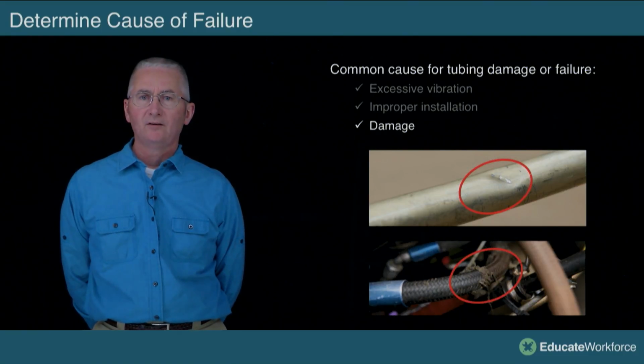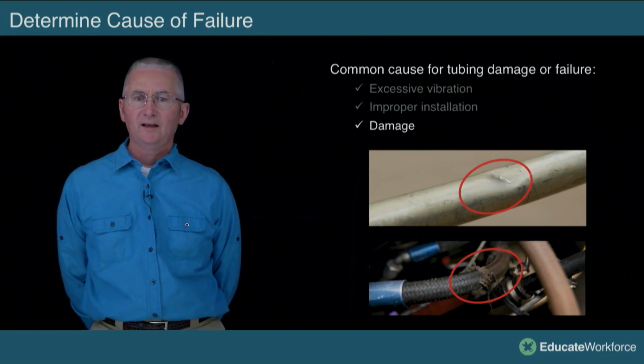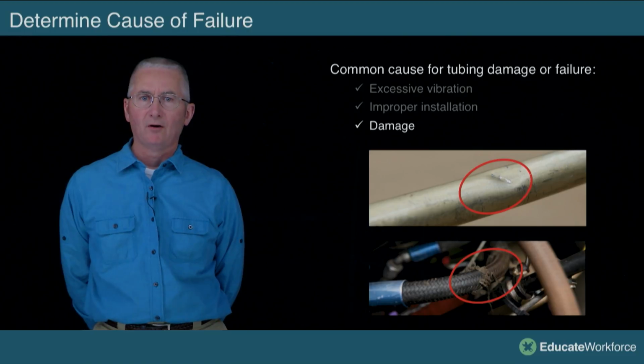And here's another dent. Notice the damage here. That's a straight line. So we're allowed some damage in this area, but looking at that, my guess is we've probably gone beyond the allowable limits. How does this damage happen? Again, maybe somebody hit it with a wrench. It might have been a tight working area where you were working or somebody else was working. Damage like this, not real common, but certainly something we have to look for on a regular basis.